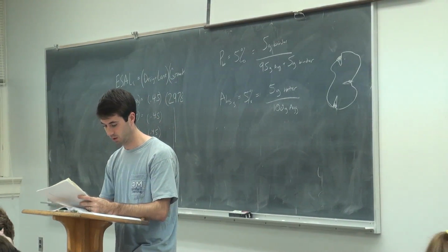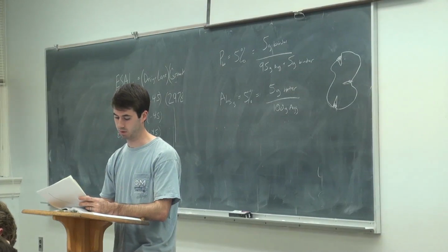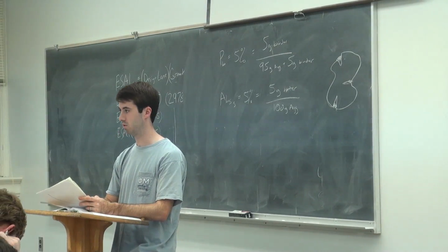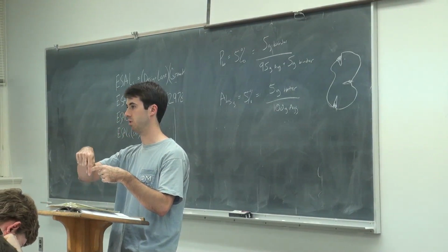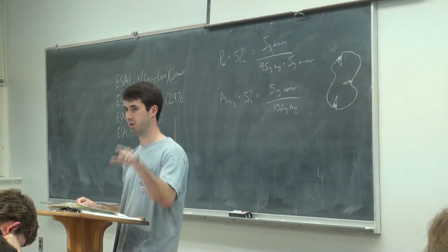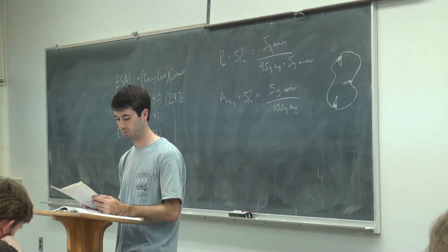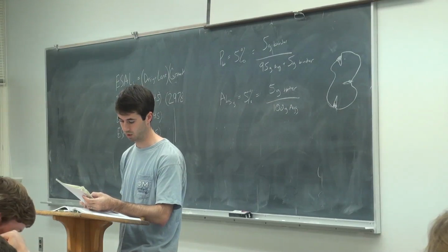And then last, you have the cold temperature. So you stick that in the BBR. It takes a little binder beam, puts a point load in the middle, and just holds it there for a bunch of seconds. It measures the deflection, calculates the beam's stiffness, and the m-value, which is similar to the sine delta thing.